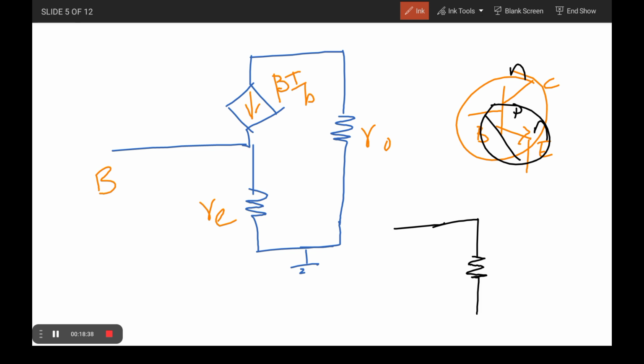At the same time, the output side can be represented as a constant current, some IC current. But practically this constant current source has a small variation in slope due to the early effect, so it can be represented with some R0 in a practical consideration.